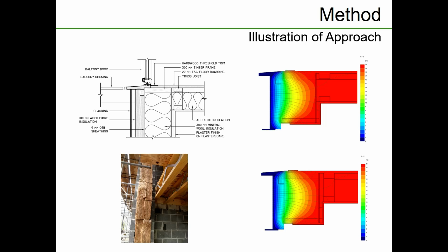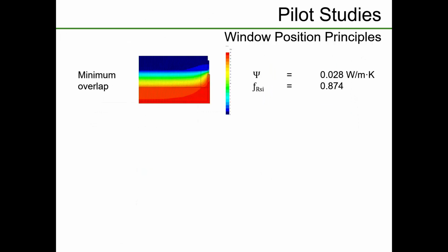Interestingly, wherever you got a balcony upstairs, you also had a set of glazed doors downstairs, going out onto a patio. Now, the design information didn't show that on this detail. There was a separate detail to show you the head of that junction. But because I've pieced all these bits together, I've modelled the design, so I've had to interpret the design to model it. The other thing as well, that joist wasn't quite exactly where it was shown in the design. It was actually tight against the wall, so there's a bit of difference there as well. But that's the illustration of the approach.